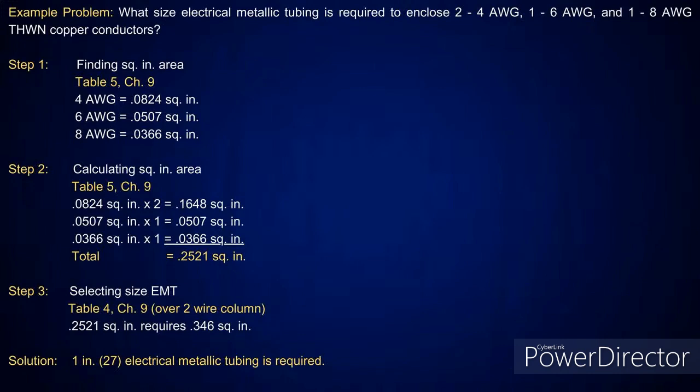You should know I'm looking at 314.16 B1 through B5, and my tables are 314.16A1 or 16A and table 314.16B. If I'm doing my raceway systems, then I'm looking at Annex C for same size conductors, and for different size conductors I'm looking at Chapter 9, Table 4, and Table 5. You should know that when you go in.